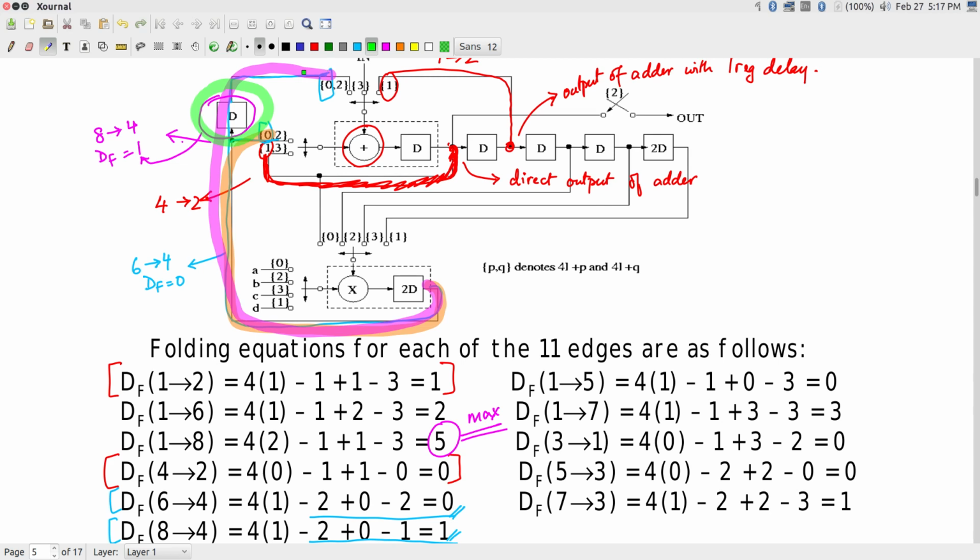In particular, if I had chosen to give this multiplier input to the other input of the adder at phase 2, I won't be able to share this register. I would have ended up needing two registers, or I would have had to do something else to my diagram over here. My diagram would have changed in some way. I might not have been able to share some of the wires at least. So there are some finer details that are involved over there that could further result in minor modifications to your design, but not very significant ones. They would mostly be relatively small changes to the design that you end up with.